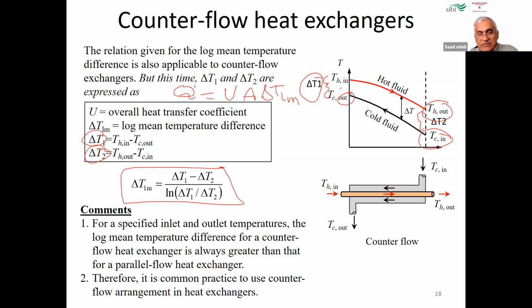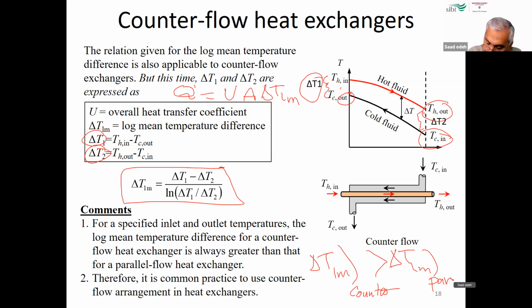So we can notice, if you compare the counterflow and parallel flow, you will find that delta T_LM in counterflow is bigger than delta T_LM in parallel flow.